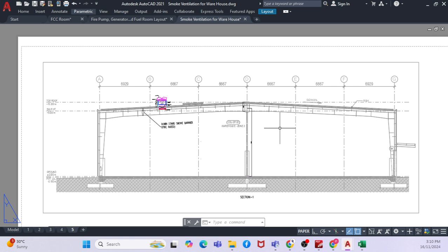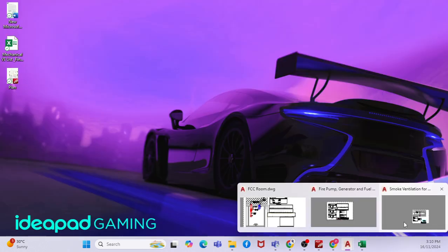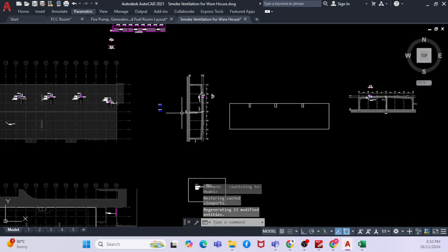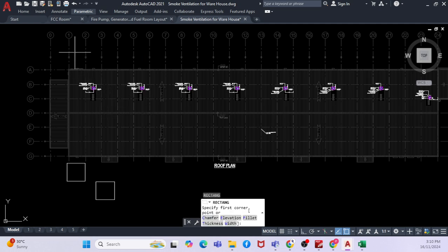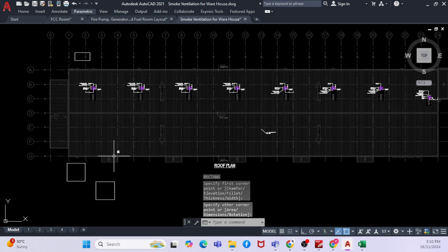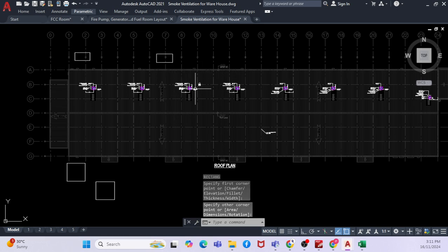But my question is, when you say downstands, that entire space, you won't be able to cross any of your ductworks, right? You're having downstands. I understand. That is why, in our design, say for example if I go to the layout, I will provide one FHU here, and this will supply only this area. Then I will go with another FHU to supply here.